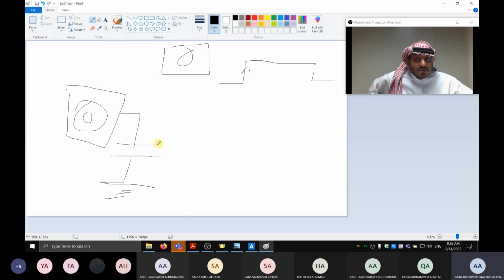So what's the capacitor doing? The capacitor by nature refuses sudden changes in voltage. So any sudden change in voltage will be removed. So that's the bouncing, and then it goes completely on. So there is only one positive edge. Yes, it's a rigged one, but still it counts as one positive edge.